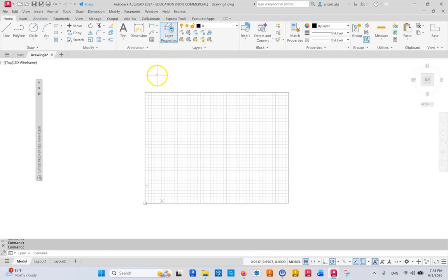Now, one more thing we need to do before we save this: set the current layer to use when you open your template, maybe object or construction would be useful. Let's do the construction. It's the guidelines. You can always change your current layer from this window, but once you open, you don't want to be on the 0 layer.